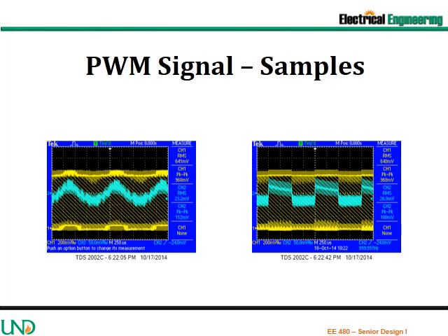The pulse width modulated signal has proved to be an effective method of transmitting signal. By sending the PWM signal to the same envelope detector as the AM signal, we were able to recover the original signal. The pulse train frequency is set to 5 MHz with a duty cycle of 50%. The deviation is set to 25%, which resulted in the cleanest sounding signal. As you can see, there is much distortion on both signals.